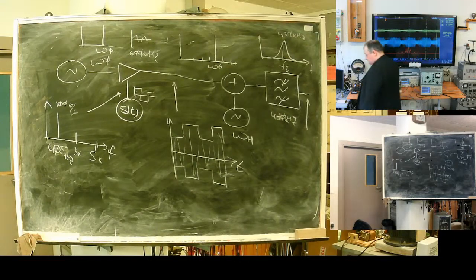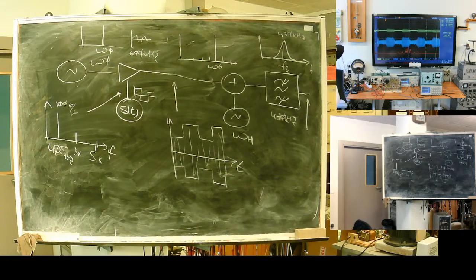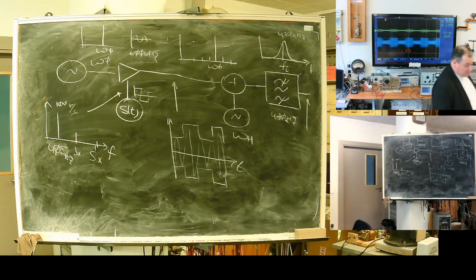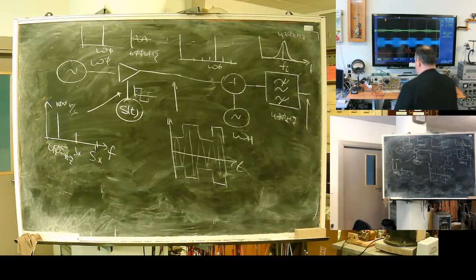I lowered the heterodyne frequency to get the situation when heterodyne frequency is below signal. To suppress the mirror channel or use an expensive high-rank system, use double frequency conversion. Not single, but double, to suppress the mirror channel.